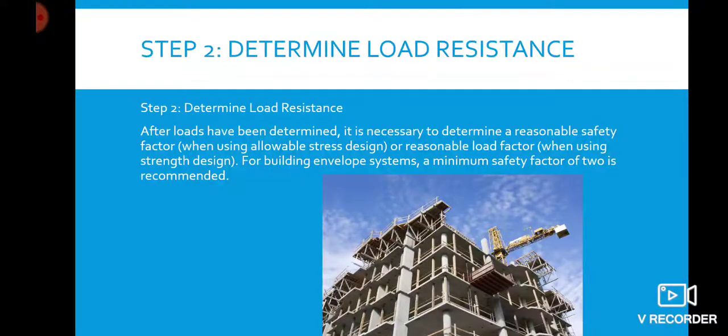A minimum safety factor of 2 is recommended, unless an important factor that is required shall be used. A minimum safety factor of 3 is recommended for anchorage of exterior mounted mechanical, electrical, and communication equipment.